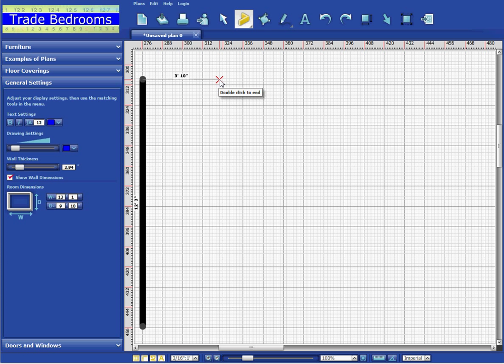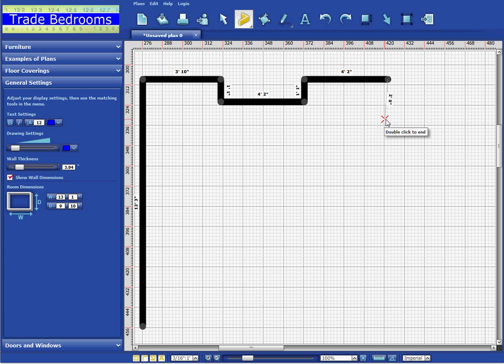to the next wall. So I'm going to do this wall as though there's a chimney breast here. So we've got a 3'11" alcove, 3'10" alcove. We drop down here to the depth of the chimney breast, we come across the width of the chimney, return. These alcoves are often different width, so we'll do that one at 4'2". Then this is coming down towards the window.